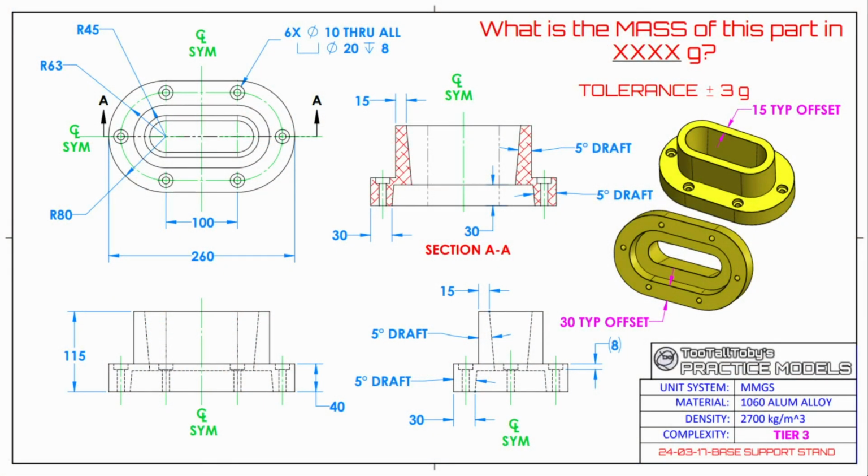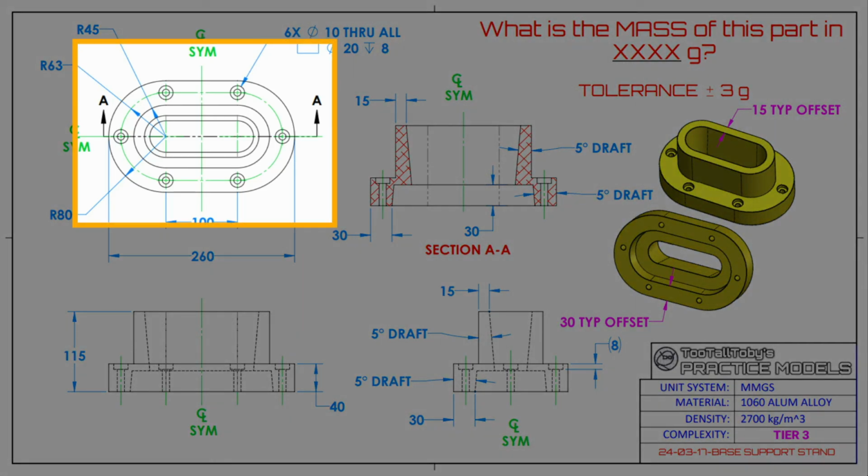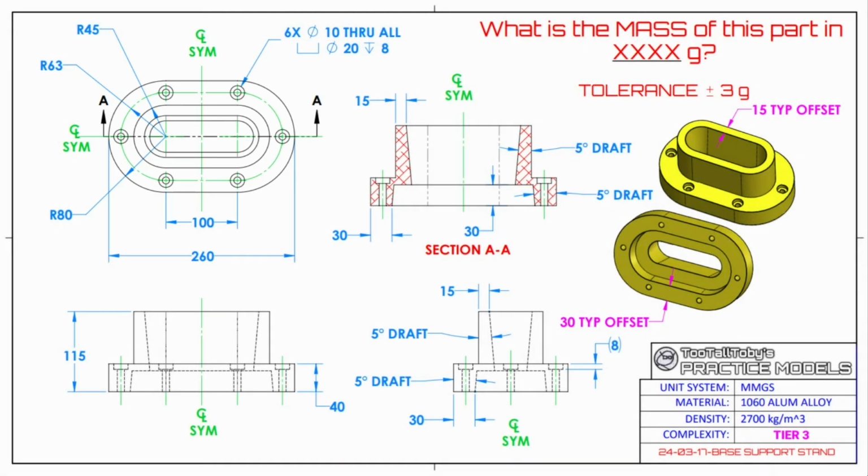Taking a look at the drawing, you notice that the main structure can be defined by basically a bunch of ovals. But more specifically, all these ovals are related to each other in the sense that they're the same shape. So the plan of attack is to essentially define this oval for the base, and then everything else will be just offsets off of this base.